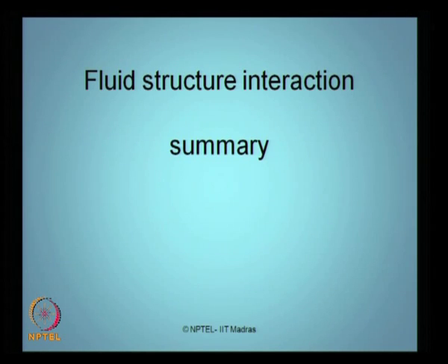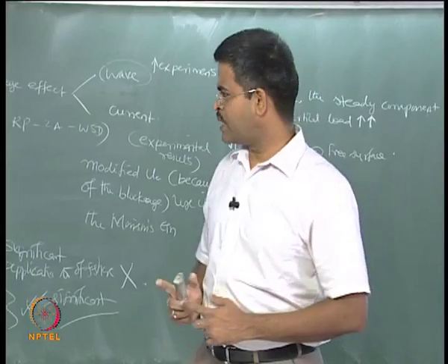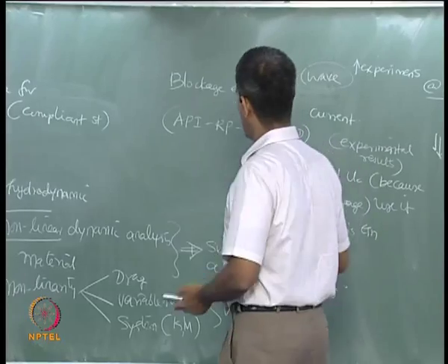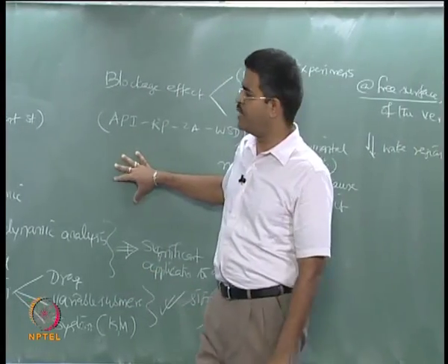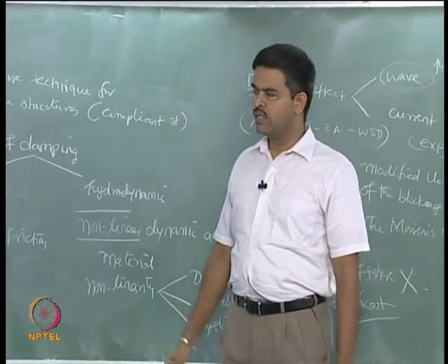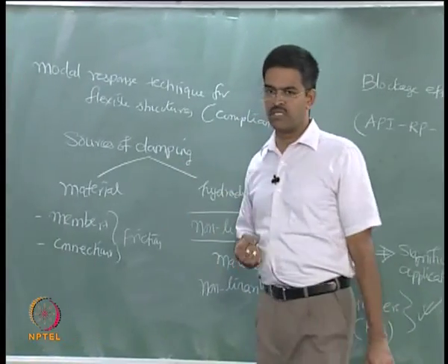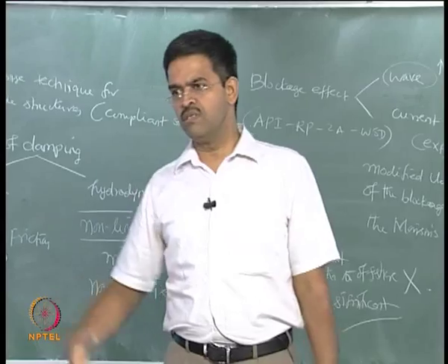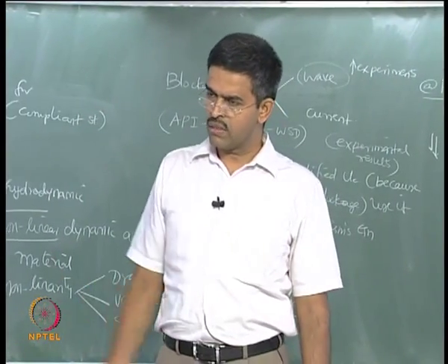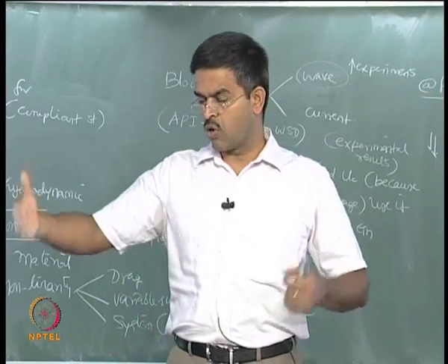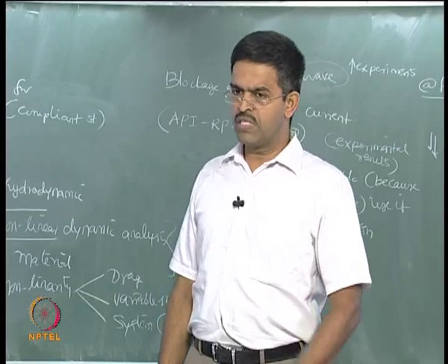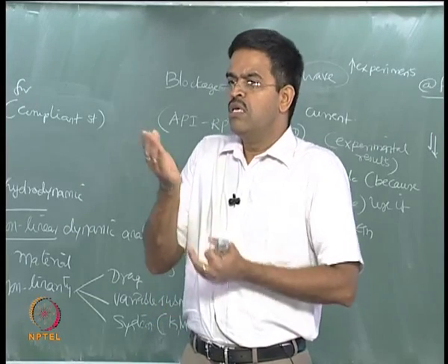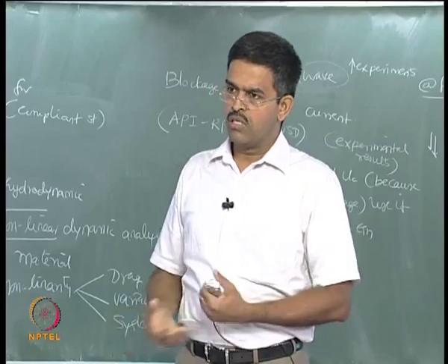So, in a very brief summary, we have picked up two examples where we have one horizontal cylinder and one vertical cylinder. We made a flow field past the cylinder. Sometimes we also discuss a group of cylinders and see the effect of these cylinders depending upon the orientation, depending upon its finite length, depending upon the boundary condition whether the ends are closed or open, and depending upon its physical location whether it is closer to the boundary or closer to the seabed.